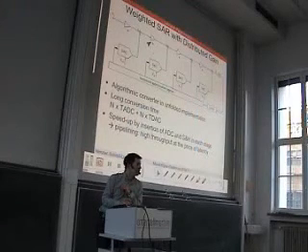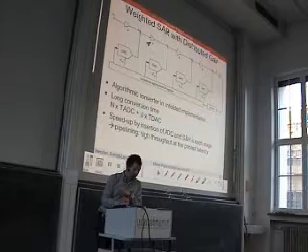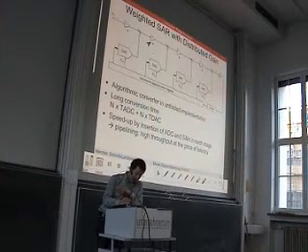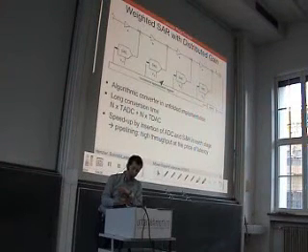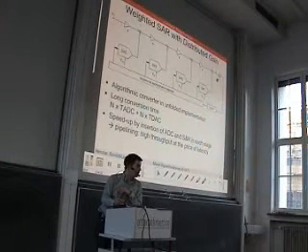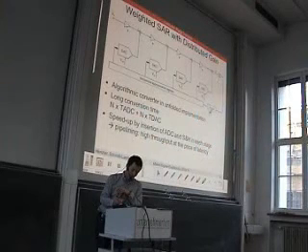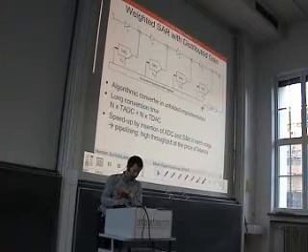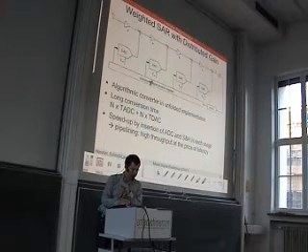So my last question was, how can we accelerate the conversion here? Well, here the conversion time is given by going n times through this loop. So we have to check n times for the sign of the internal voltage. Then we have some delay in the control register. We have to switch the DAC, so we have to wait for the DAC settling.